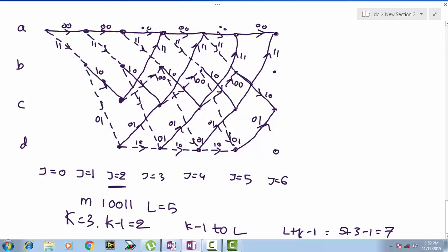Now this is j equal to 6. Now we got only two states, A and C. Again we need to consider only input bit as 0. So now when the input bit is 0, we move to state A with output 0 0. And now in state C, when the input is 0, we will move to state A. Okay, so output is 1 1. So this completes your trellis. As you can see, this is the last level, which is j equal to 7.